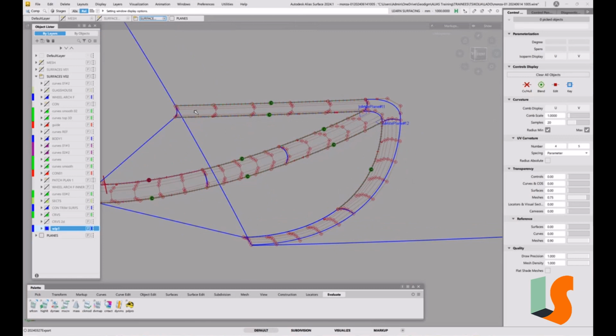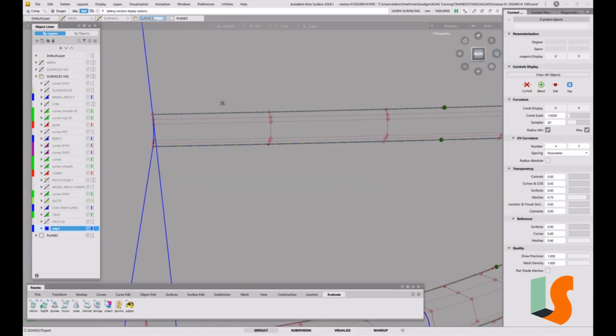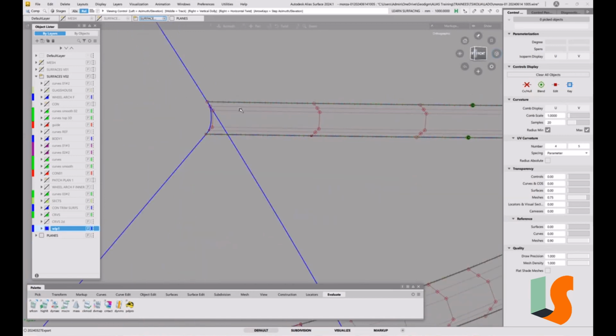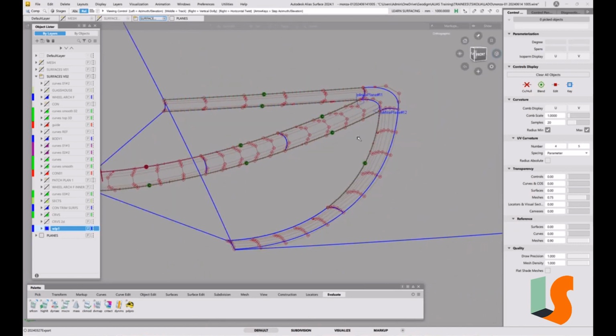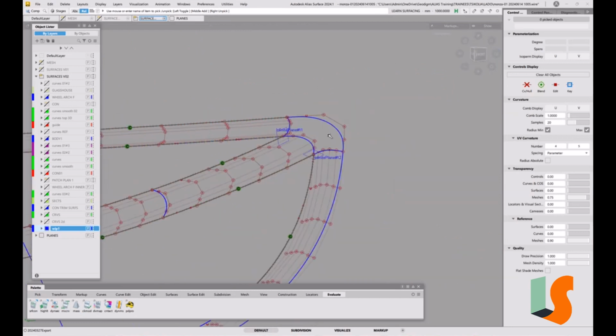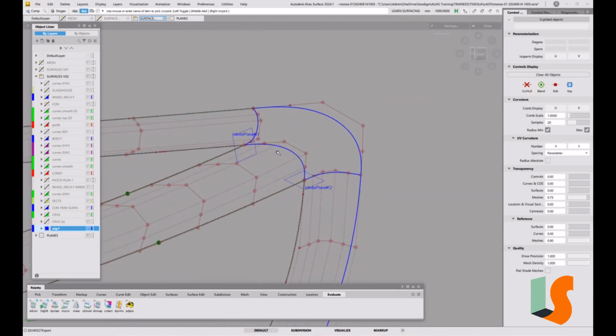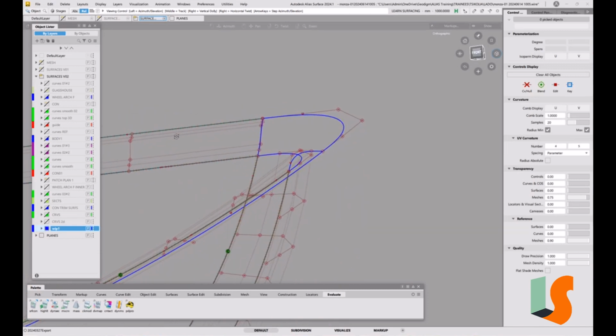What you will find is when you fillet things, even though you've aligned it everywhere, when we mirror the whole thing across, you might find that the ends don't quite align. That's a possibility. When we get to that point, then that's something to worry about, but it's not very significant. It's easy to fix, but it's quite common that's what happens. So around here, I want to get rid of these. I don't really need these planes anymore. I could keep them in a construction layer. If I was working on this in reality, I probably would do that.